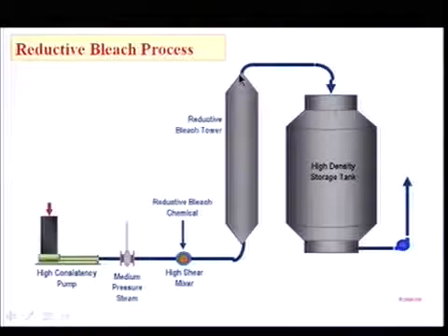All the chemicals are in. So, you can drop from top to bottom. You do not have to worry about air taking away your chemical, because the chemicals are already in the fiber. There you store at high consistency 10 to 12, and then dilute at the bottom with the white water and pump it to your paper machine for making bright, nice paper.